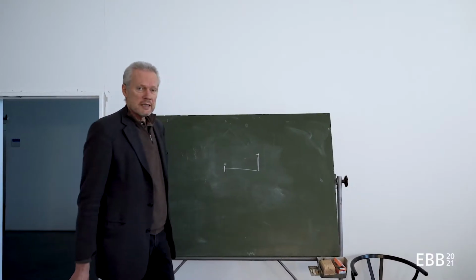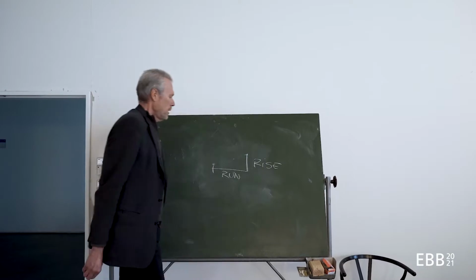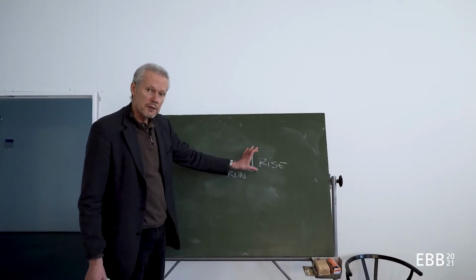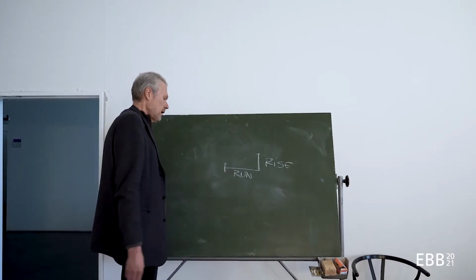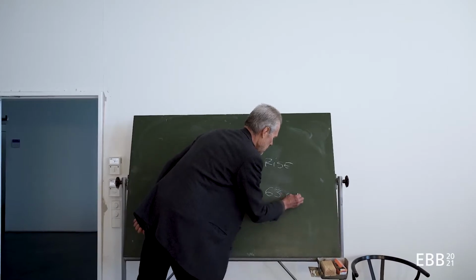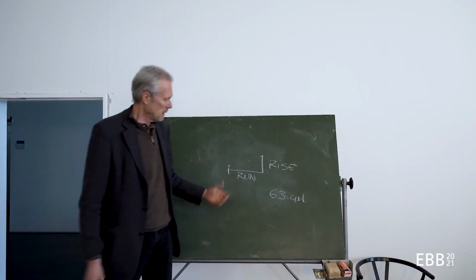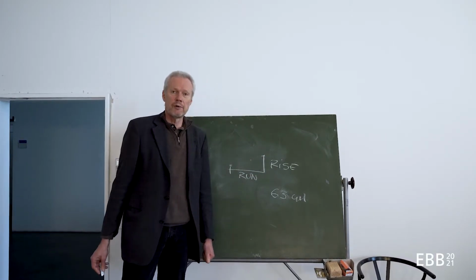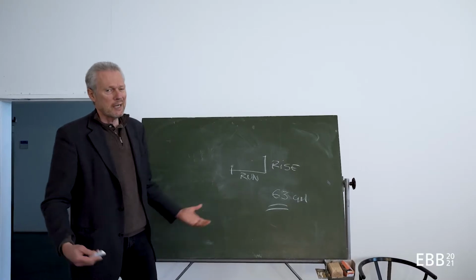To start with the stair, it's important to know more about the slope of a stair. So if we have one step, there is a run and a rise, and the relationship of two rises and one run, if I add them up, should be 63 centimeters. So that's the run-rise ratio, which should add up to this. But there are other rules.